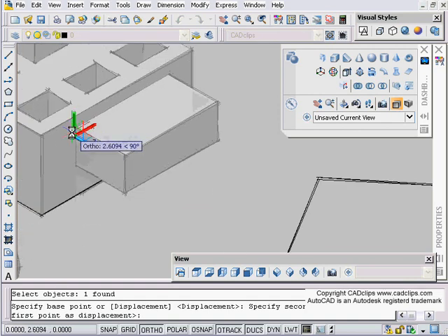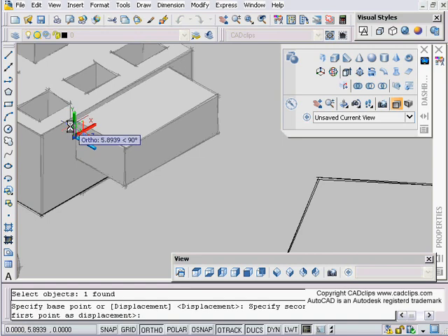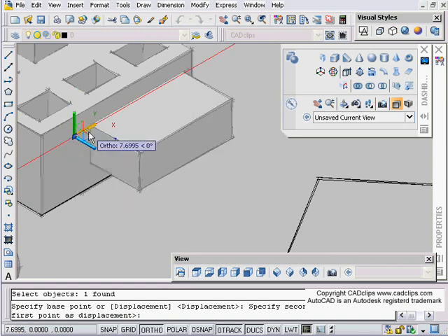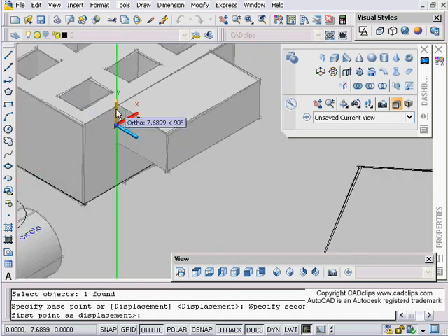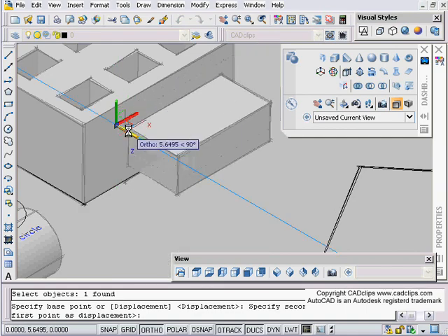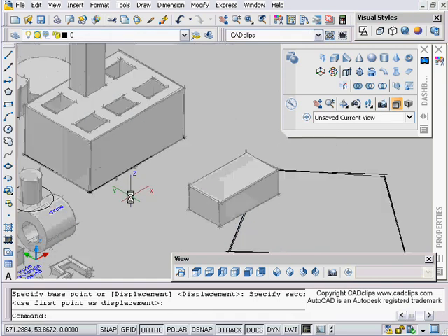is all I'm saying. So when you do your push-pull off of a surface, it creates the new object as part of the original object of the surface it was dragged on. So maybe do a repeat of that exercise. Whenever we see these axes, before we finish our placement, we're free to pick an axis that we want to drag along and then place that out.